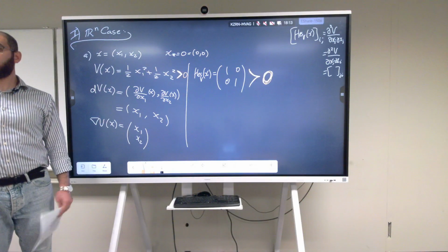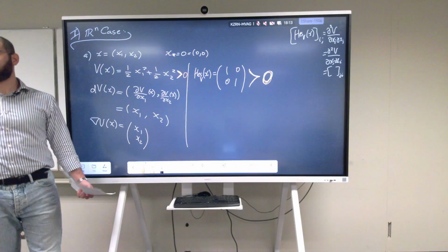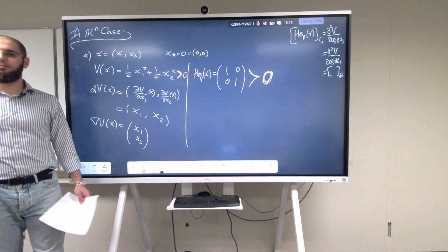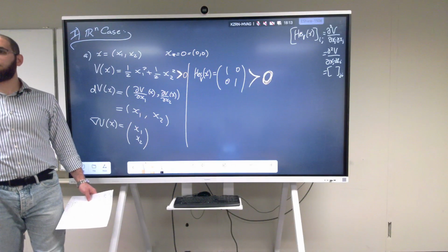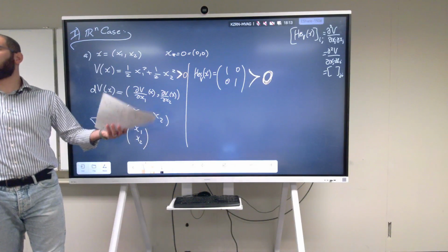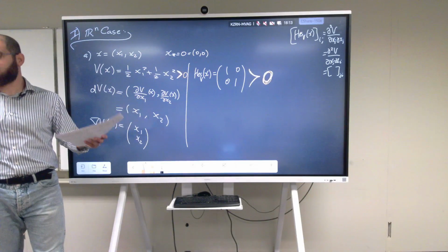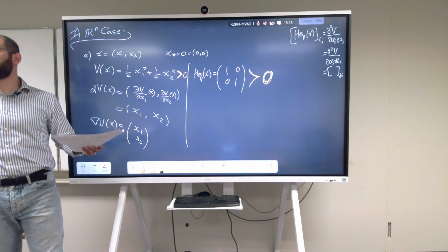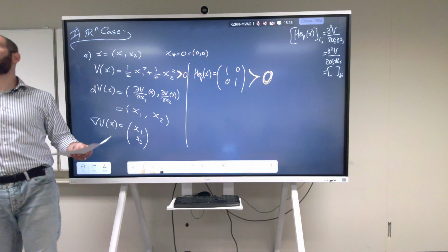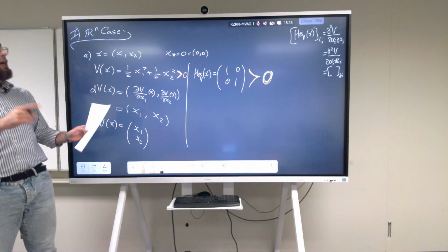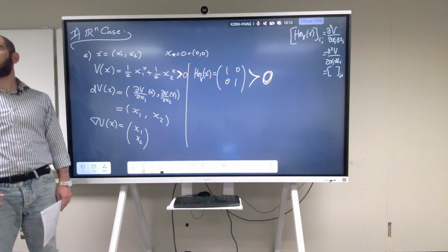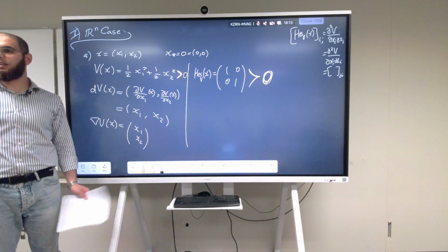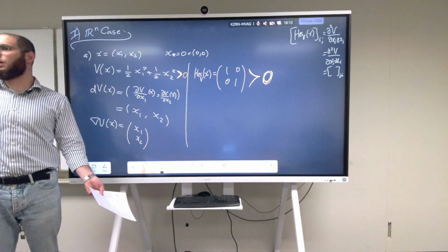No, what is stable? Not yet. No, this is positive definite. Not yet. What is stable? Did we even do Lyapunov? No. I'm just giving you a function, telling you to check whether it's positive definite or not. I did not take the time derivative of it, because to calculate the V dot, what is missing here? The x dot. The dynamics itself. What kind of system are we talking about?